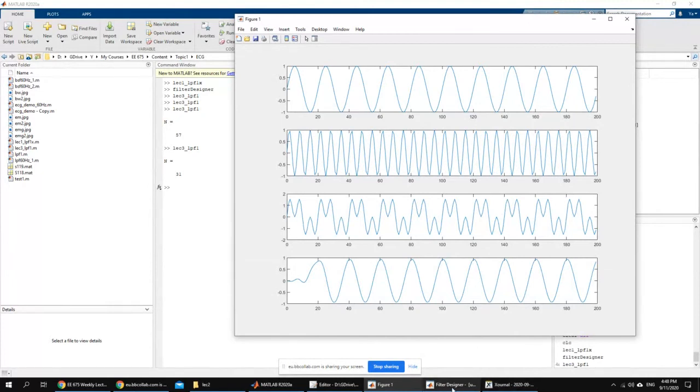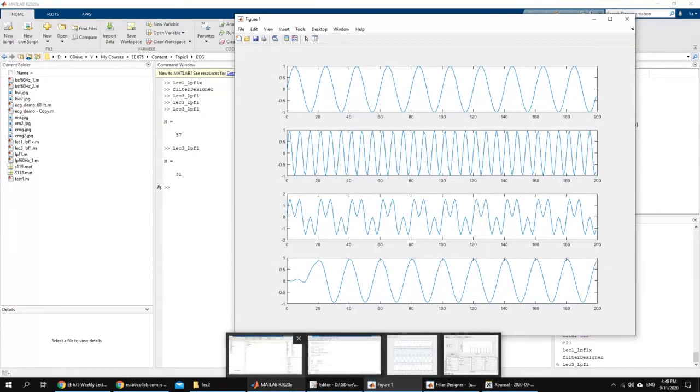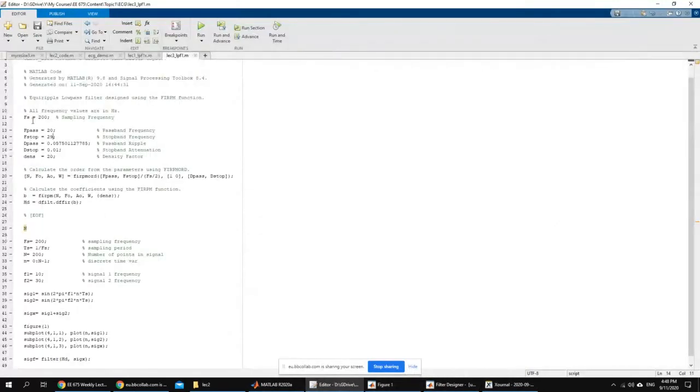So if you do it this way, this will help you optimize the parameters of the filter just right here, instead of having to go back and forth between the filter designer tool and your code. And each time you generate a new code and copy this part here and try again, you don't want to do that. Okay, you just do the design once, and then change the parameters for the same design on this file, and that's it.